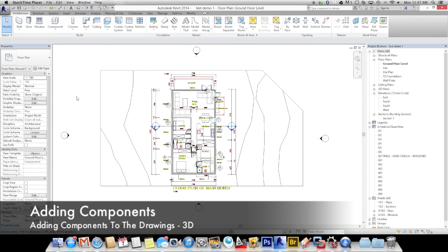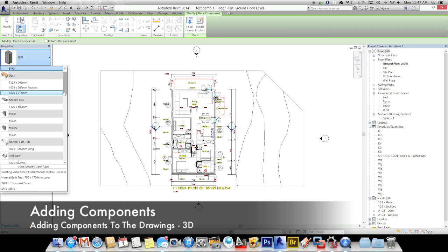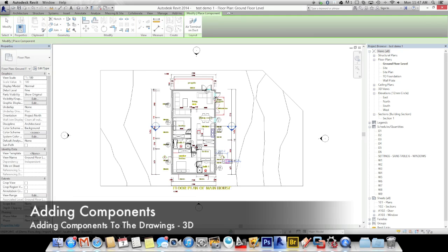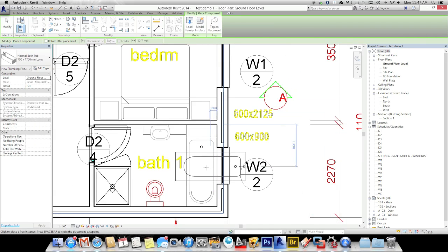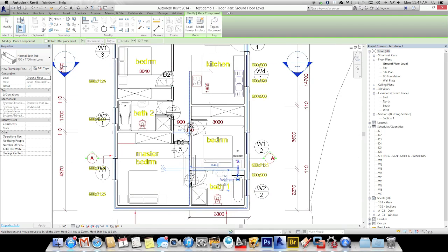To add plumbing or basically any kind of component, you go to Components, you go to Properties, and to the drop down menu. There you just search for the type of component that you want to add. Once again, if you zoom in and use your space bar, you can position it in the orientation you need to. And then just place them.